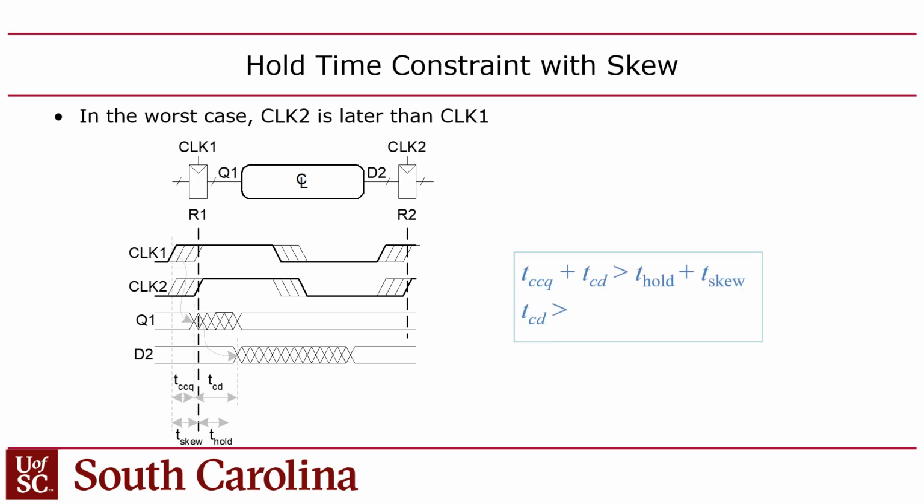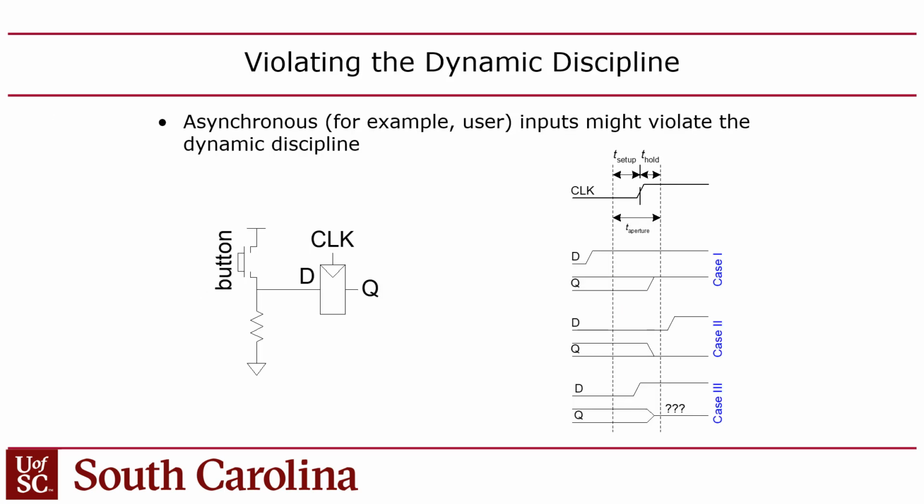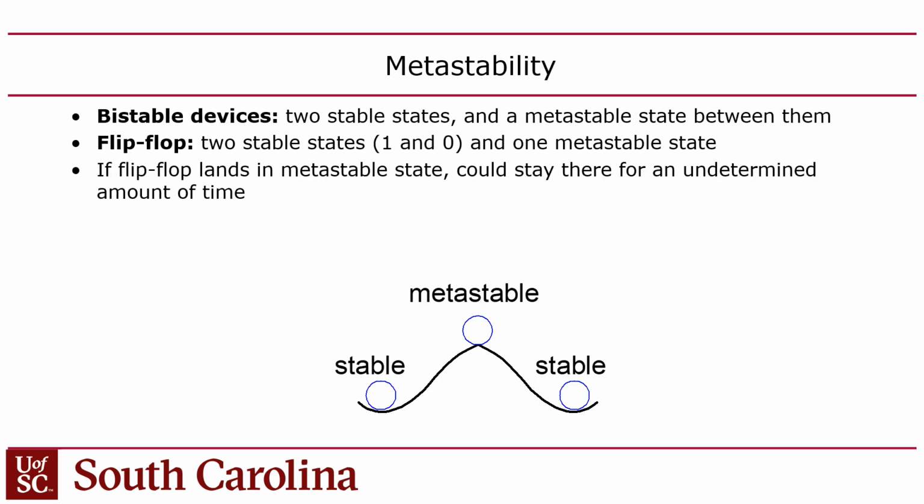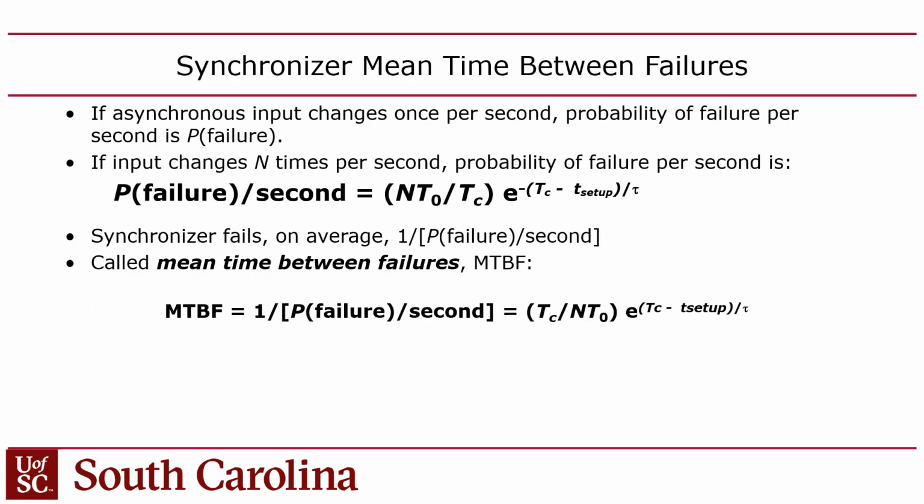For hold time, on the other hand, what happens is you end up having to subtract the skew relative to the time you're calculating for your contamination time. So you calculate your contamination time and you're backing the skew out of it, meaning that you're saying your circuit is maybe faster than you calculate it to be because of the skew. Now, in this equation, instead of subtracting the skew from there, they're adding it to the other side, to the hold time, right? Okay. So let's look at the same example, oh, I'll come back to the example.